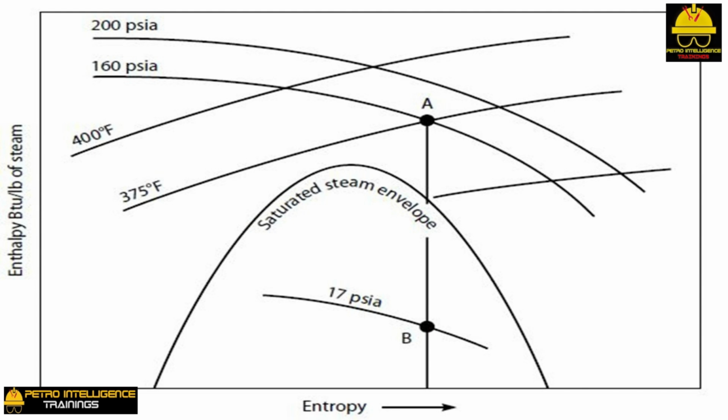7. Multiply the horsepower per pound of steam calculated in step 6 by the turbine steam flow in pounds per hour. This is the total shaft work that appears at the turbine's coupling. This is the amount of horsepower that is available to spin a centrifugal pump or a variable speed air blower.